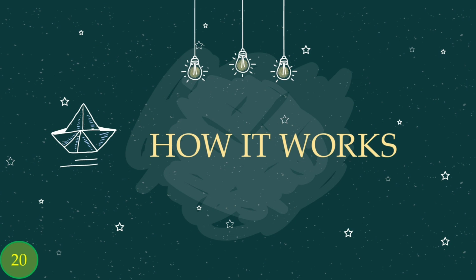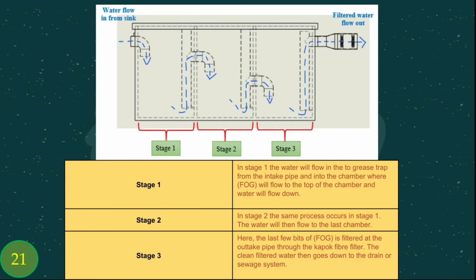Next, I'll talk about how it works. In stage 1, the water will flow into the grease trap from the intake pipe and into the chamber, where fat, oil and grease will flow to the top of the chamber and water will flow down. In stage 2, the same process occurs as in stage 1. The water will then flow to the last chamber. In stage 3, the last few bits of fat, oil and grease are filtered through the carpet fiber filter to the outtake pipe. The clean filtered water then goes down to the drain or sewage system.